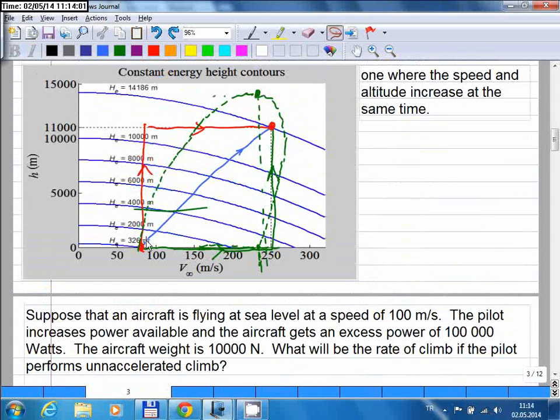You just increase the altitude at a constant speed, because that's what we can easily calculate analytically. But as I said earlier, if you want to find the time to climb during an accelerated climb, you can do this numerically by writing a computer program. Nevertheless, right now we are only talking about climbing at a constant speed.